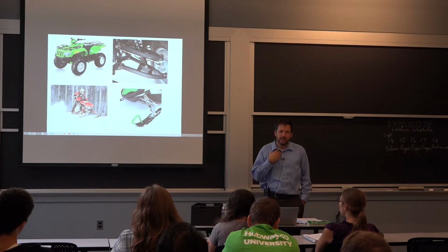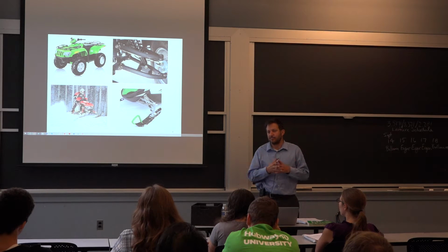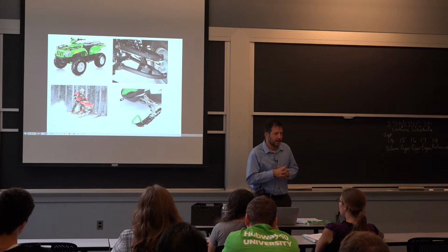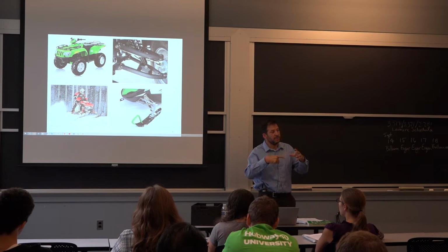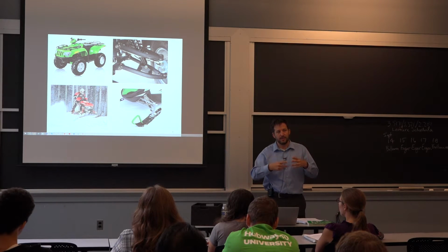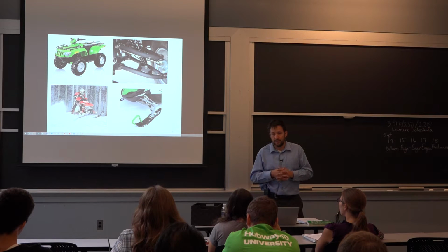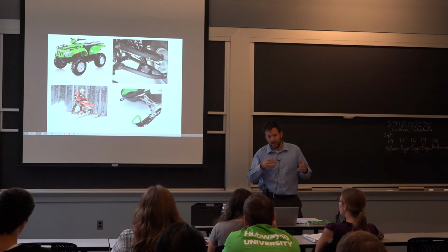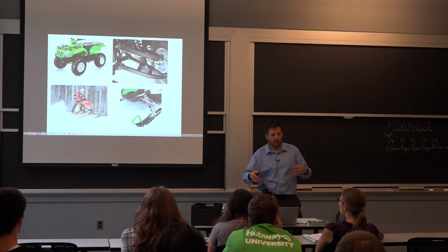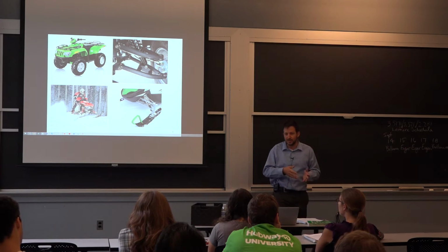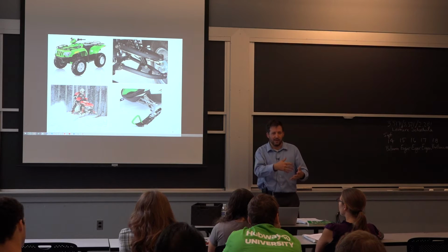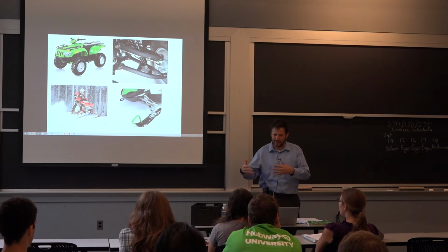Does it really need to be lightweight? Well, that's up for discussion because it's not really part of the wheel itself, so it doesn't get accelerated. But it's part of an assembly that people try to make light. These vehicles will weigh something of the order of 800 pounds, and therefore each 3-4 pounds you add per wheel of extra material does make a difference. And they get compared from manufacturer to manufacturer for that difference.